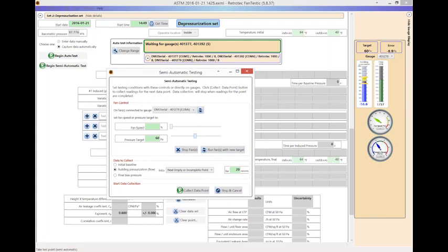Okay, and then just try adjusting your fan speed, and you can see there that. Try to do speed or pressure? I have pressure set here. Well, actually, it's already operating, so yeah. It's clear that yes, it can achieve 60 pascals. You can see it overshot there a little bit. It's now at 61.7. So what that's telling us is that fan is working on both channels. Channel A is giving you the pressure, channel B is giving you the flow, and using the same method you can go and you can check each one of your fans individually to see whether it's working.